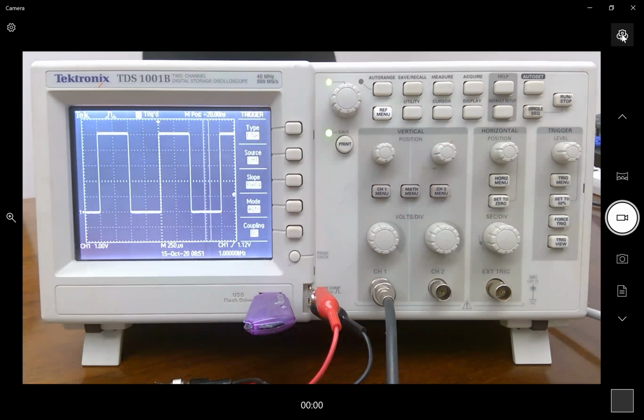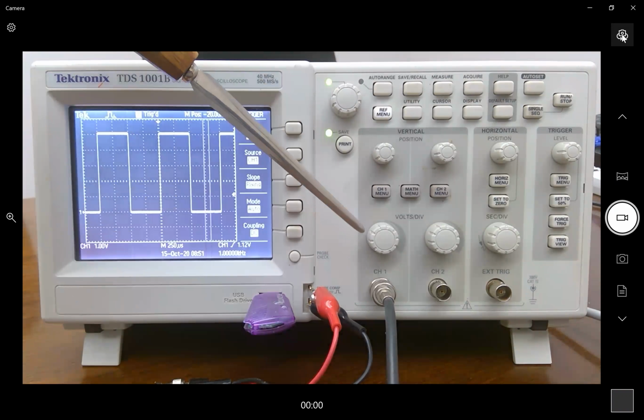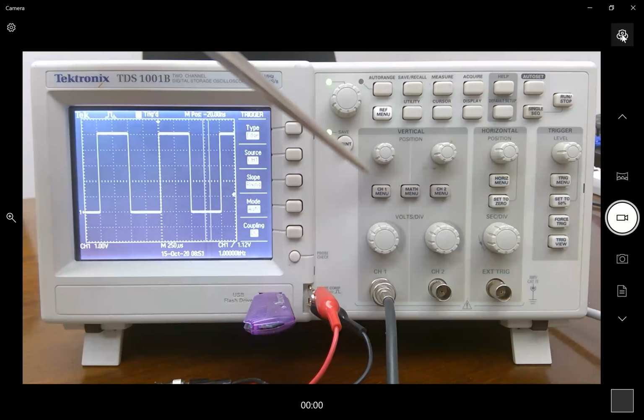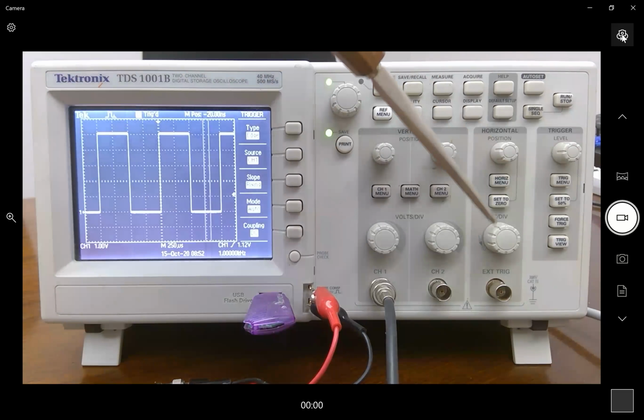So actually, I want to go through some of the different actions you can do with this oscilloscope. I may get a bit louder because I'm going to be reaching over this. Your oscilloscope, here's your screen, here's your volts per division with your menu. You have a vertical position, which changes the positioning of the signal. And then you have your horizontal position, your times per division. This is your trigger menu again, and then all the cute bells and whistles.